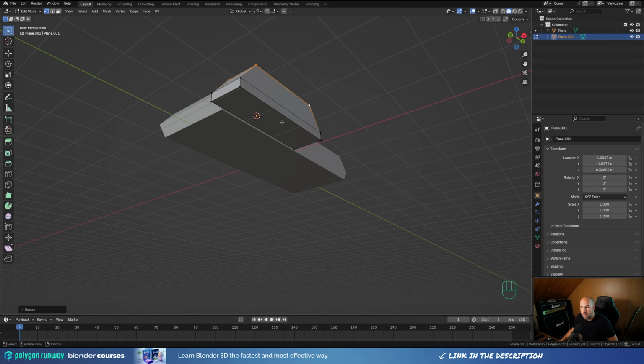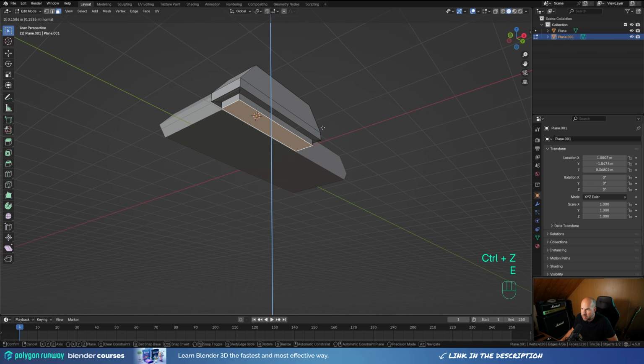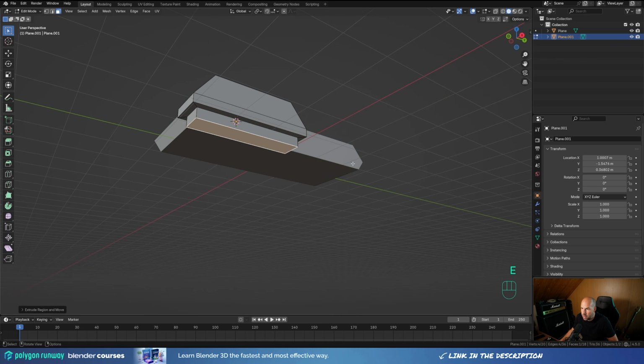Now these won't be any like rigged or moving tracks, because from a top-down view you wouldn't see this moving in any way. So let's just press 3 for face select, select this face right here, press I to inset, and now we'll just press E to extrude this down, and then S then Y to scale it like this. And now let's go for edge select right here, alt click this loop, and we'll press V to separate this and right click to release it in place. I want to have this as a separate mesh so the transition is sharp there.